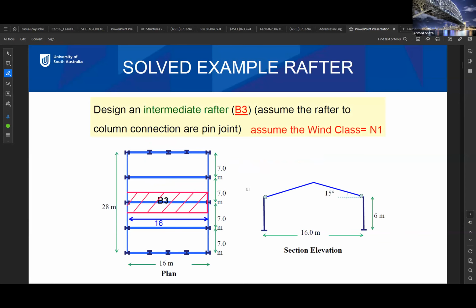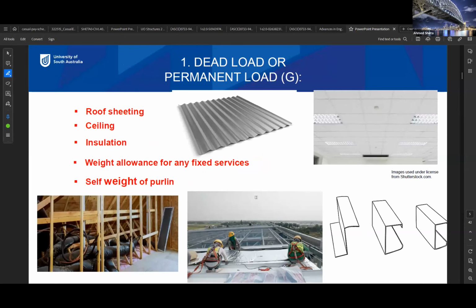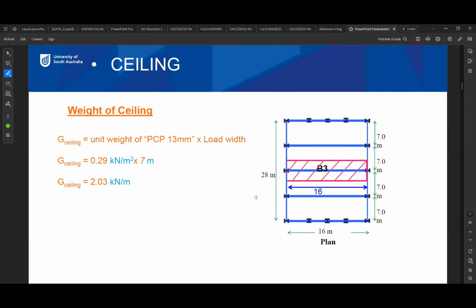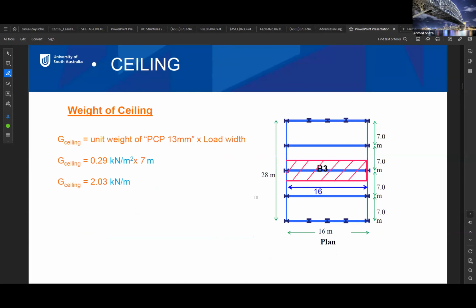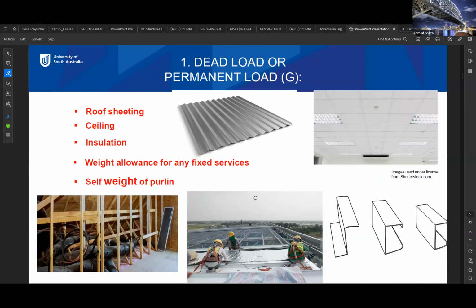So if you go step by step with this example, you can get all the loads correctly on B1. Excellent. Because B1 is still a roof beam, B1 still has wind load, uplift and pressure, and the same load combination. So the only difference is that it is not required to design B1 in the assignment.